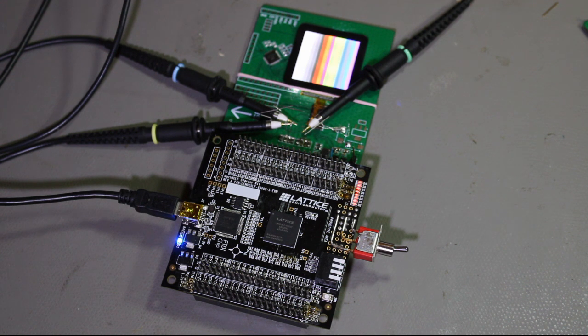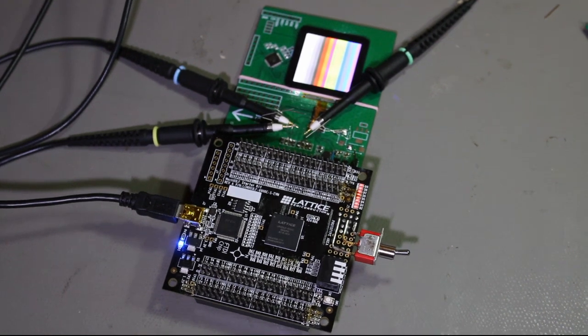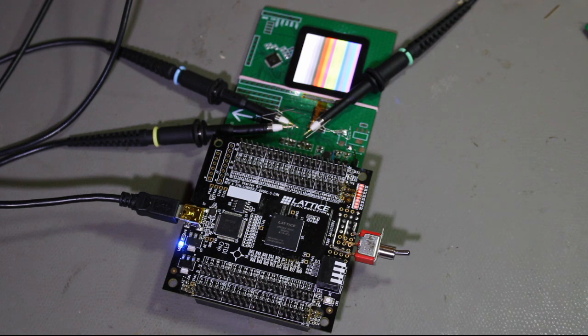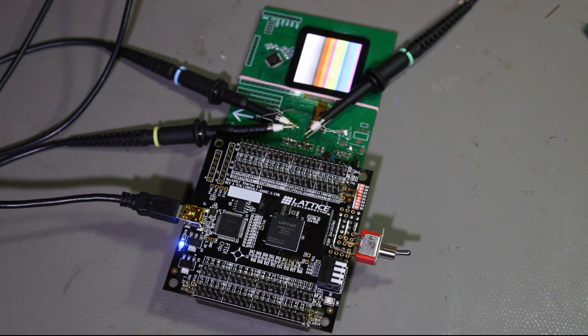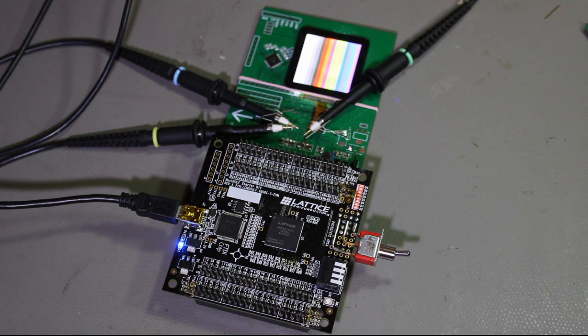This video will focus more on what it takes to implement an FPGA module to drive these MIPI displays. I'll be explaining what it effectively takes to implement a SPI to MIPI DSI bridge, so that we can connect this display to a microcontroller over SPI and directly drive it using a microcontroller, having the FPGA as a bridge in between.